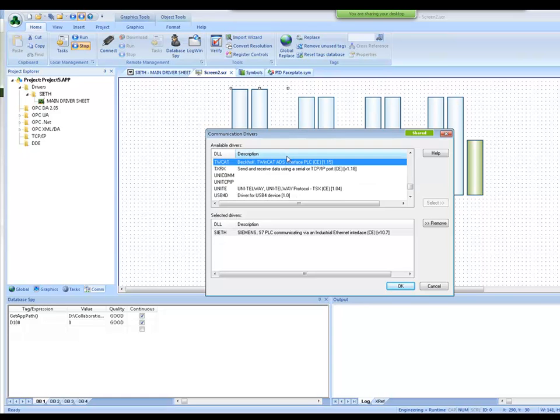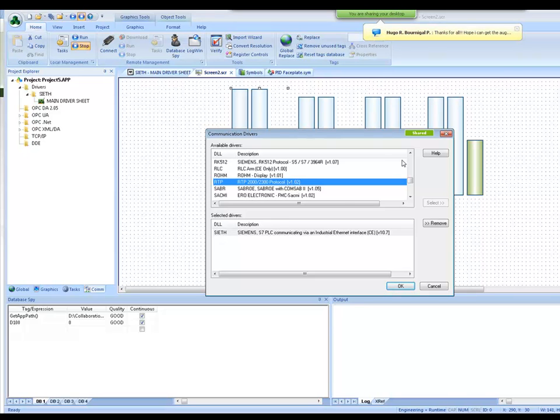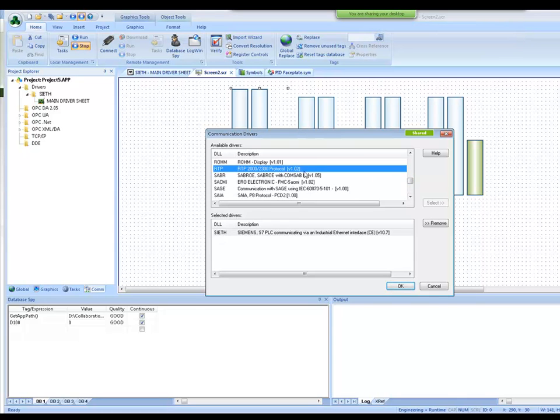So for instance, with Beckhoff TwinCat, we can read every 20 milliseconds. With the RTP, we can get a reading every 30 or so milliseconds, and that's per group. And since we have the parallel communications, you can have several groups being read at the same time. So the drivers that we use, all of this here. In the case of the Brookhaven specifically, he's using the RTP driver. I don't know if you're using any other driver, Patrick.